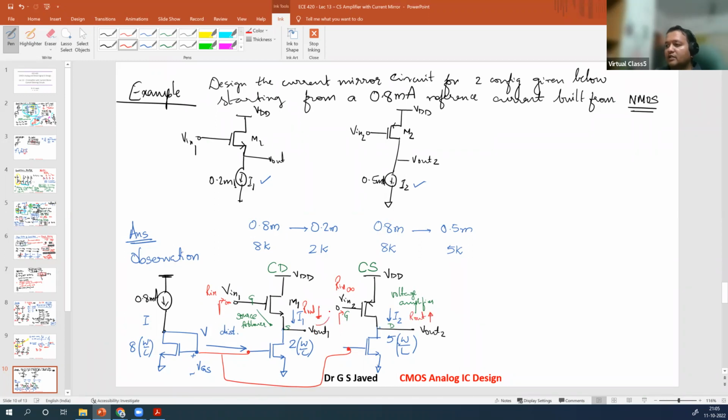Now, if you connect these two, small input to infinite impedance, what will happen? You will have an impedance break. Now, if you put this in parallel, what will be the effective impedance of these two circuits put together? Low impedance in parallel with a large impedance will effectively give a low impedance here. So, interstage impedance will be low, low to high. You will have gain mismatch.